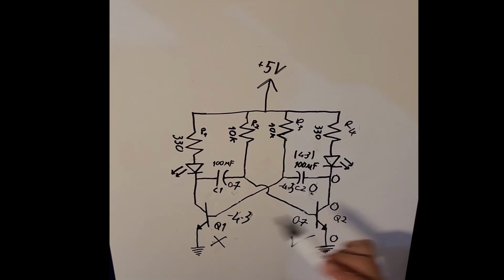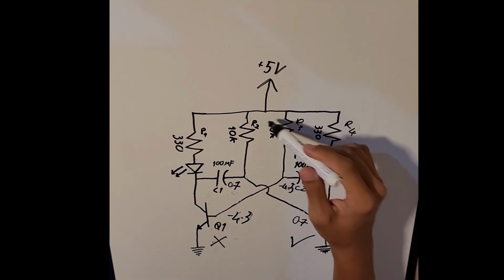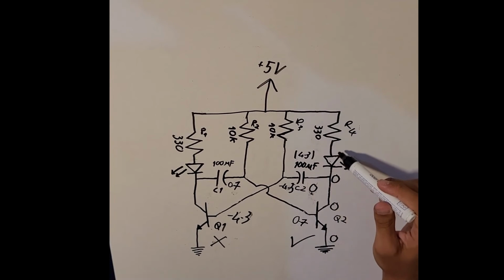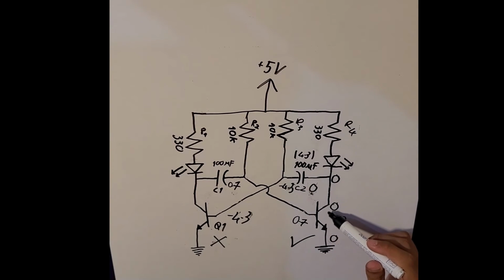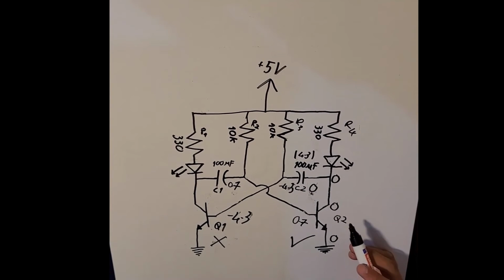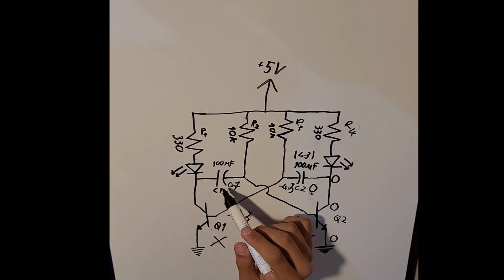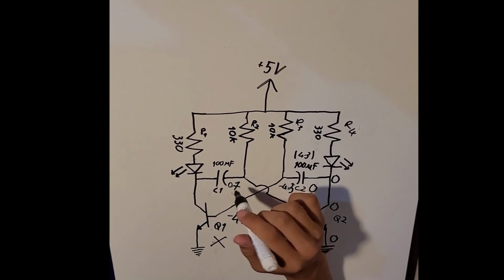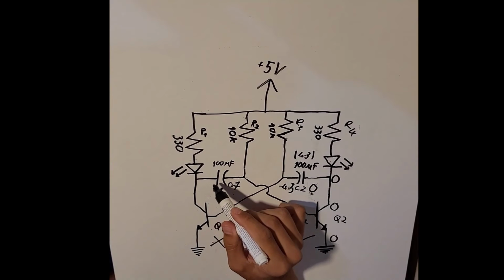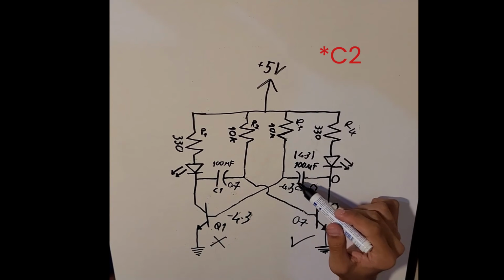And when this cycle goes on, during the time the transistor is on, for example Q2, the current will go through R4 and our LED through here, and our LED will be emitting light. And the thing that sets the frequency is the discharging time of C1 in this situation. At the beginning, C1 had 0 volts here, and negative 4.3 here, like C1 has right now.